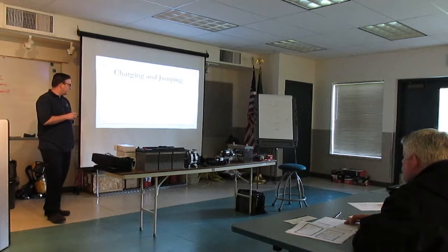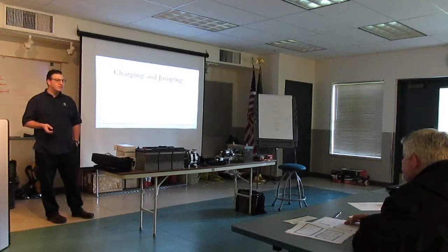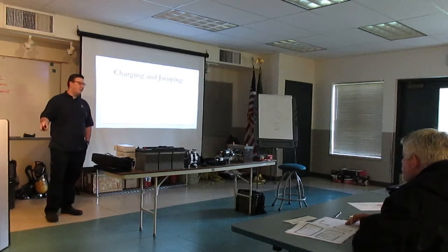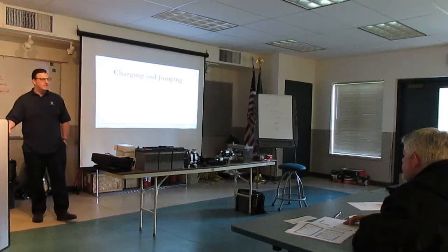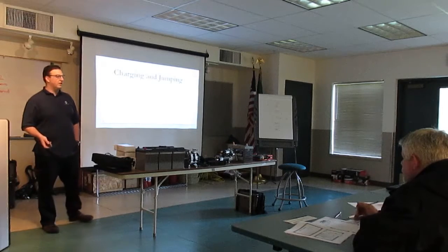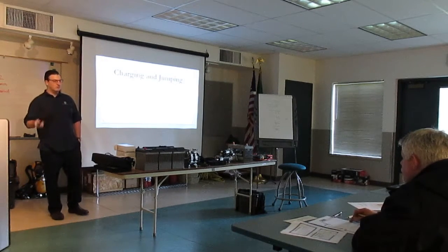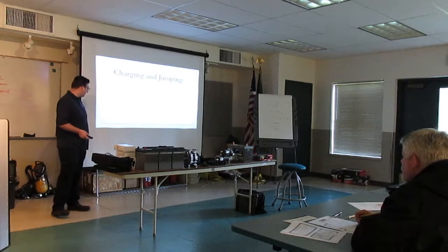Again, your vehicle charging system may not be properly diagnosed unless the battery is at least 90% charged. So if you come up to a vehicle that has dead batteries, you have to charge them up before you can start ruling out whether it's the alternator, a battery issue, a cabling issue, or some other issue going on with the vehicle.